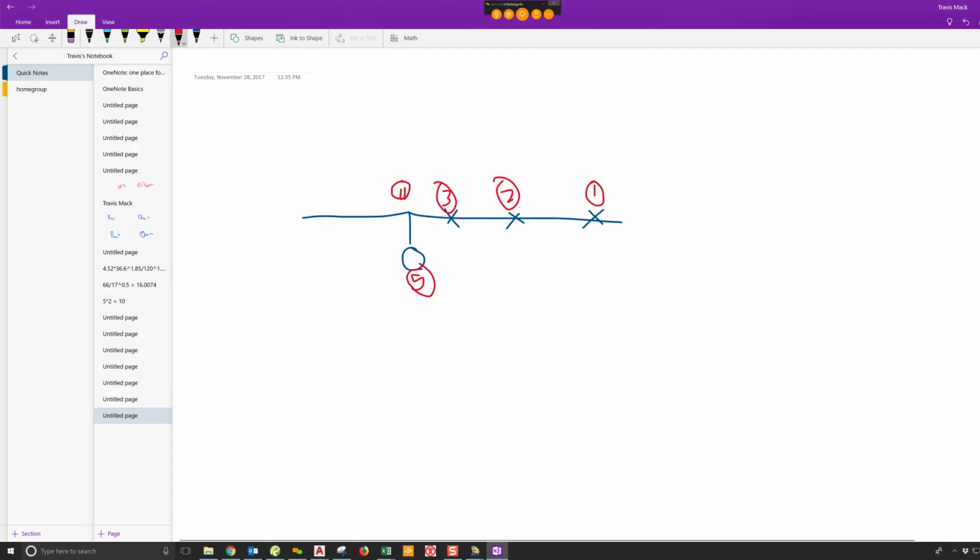Guys get how to tell which fitting goes on what pipe wrong all the time. So we calc everything backwards. Okay. So we start from the end head and come backwards. That's our demand calc. So what we're figuring out is what is the absolute minimum flow and pressure we need to make things work. But the way that we figure the fittings into these formulas is that the pipe is going, or we're running our calc back this way.